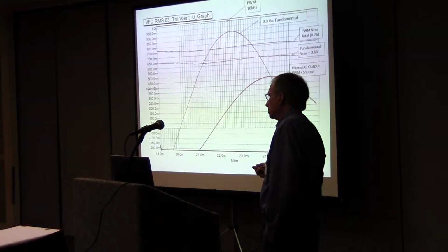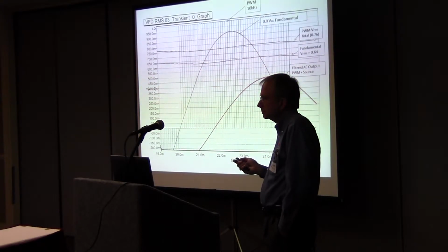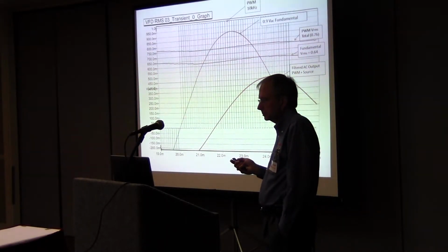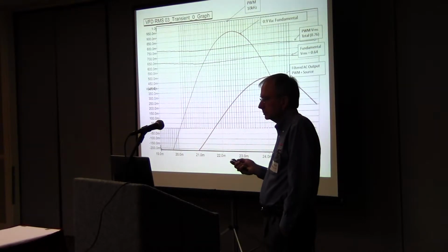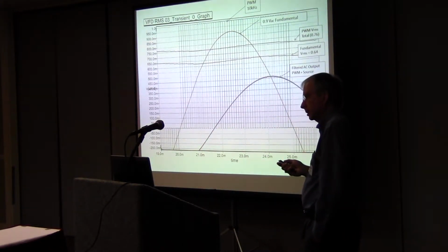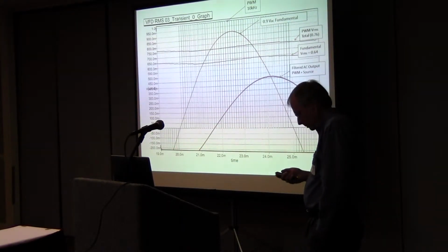And I'm sorry, I kind of lost your question. But well, if I'm looking at the RMS, and my motor is filtering out the harmonics, then when I look at it, I'm seeing 60 hertz, and the RMS is what I'm wanting to see. But if it's not filtered out, then it's going to alter the voltage I'm seeing on my meter. That's what I'm trying to.